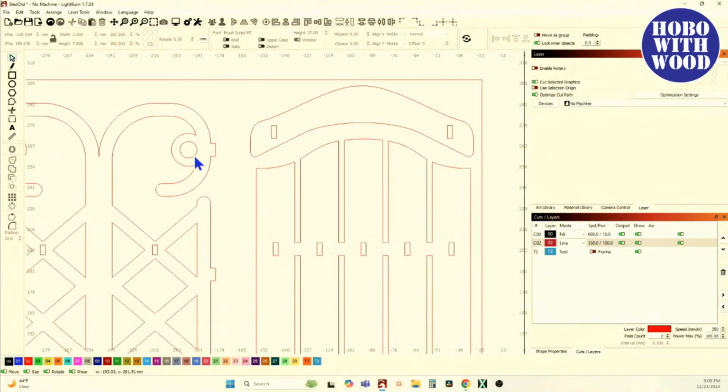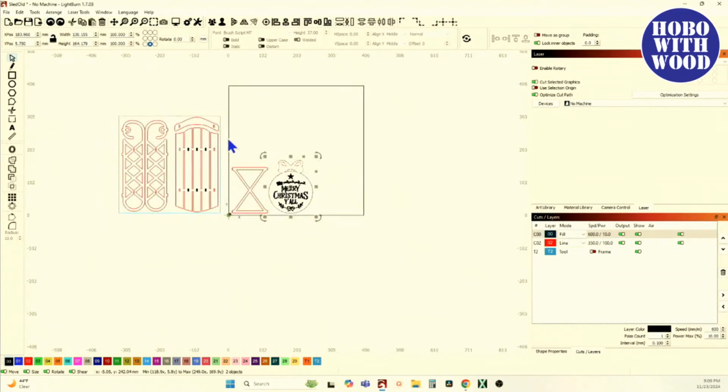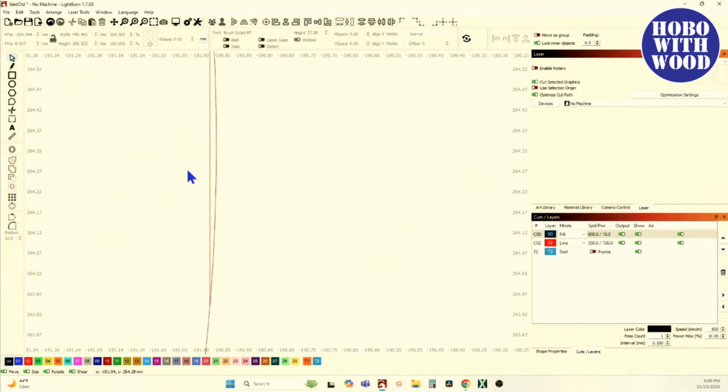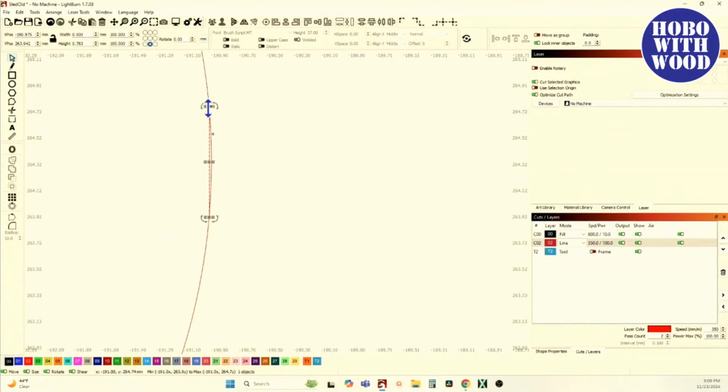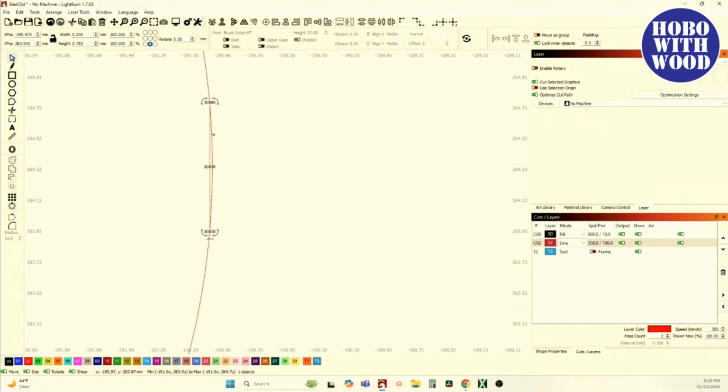Now, I didn't do this when I was looking for the problems because I wanted to identify where the problems were at. And I want to show you this because I think these were a result of the scissor tool. So I'm going to undo what I just did. In fact, there were 2 items in there, and when I did that 0 offset, there we go. Now let's get that back over here. And yeah. All right. See here, there's a straight line right there. That little bitty straight line is a remnant of a piece that was left after using the scissor tool.